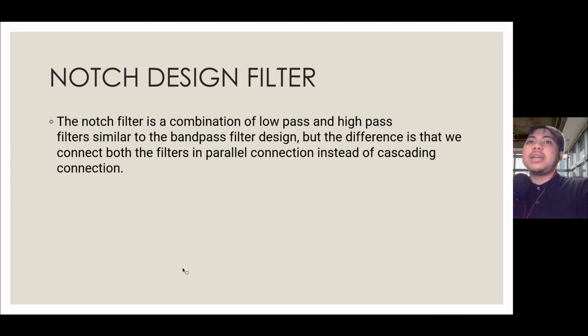In this lab, the desired filter can be designed in several different ways, providing a different amount of flexibility for future modification. Before starting any filter design, you should carefully characterize or identify the signal to alter. This will allow the creator, who chooses the filter, to determine the filter configuration to be used. For example, the goal of a particular filter might be to remove noise above a certain cut-off frequency. So in this case, a low-pass filter might be used.